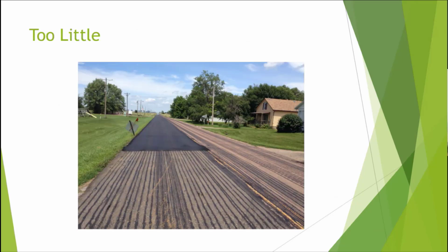But don't underestimate the tack coat. This one I've had for a long time is a picture I took quite a few years ago in southeastern South Dakota. Well, what you see there is not tack. I guess it's delineation to keep you on the road if you've had too many to drink. But I'm sure what happened here on this county road is that they had so much tack left, and the county road supervisor said, hey, take that load out and shoot between so-and-so's place and so-and-so's place. We're going to go out there and do some patching. Well, they didn't have enough to spray it the whole way, didn't know where they were going to patch, so they spread it out too thin over 4 miles instead of the right shot rate where they were going to patch.